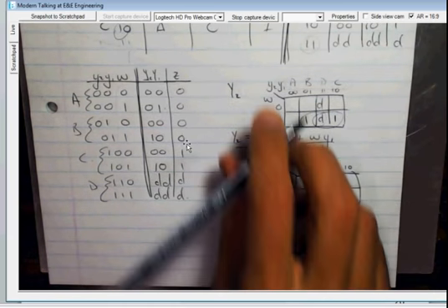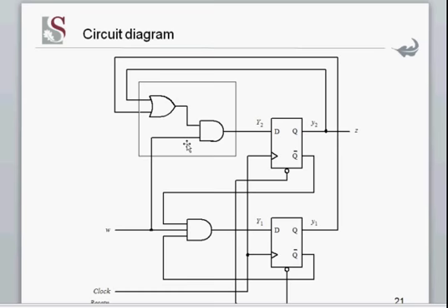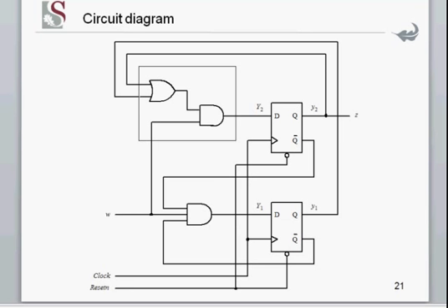So that means you can draw this diagram out, and it looks something like this. That's what we've just designed. We've just designed a circuit that will perform this function. Important thing to understand, yet again, is your flip-flops transition to what the logic says the next state should be. I'm going to say that again. The flip-flops make that state transition to what this block of logic, the next state logic, says the next state should be when there's a clock edge. And the output is just dependent on your present state.